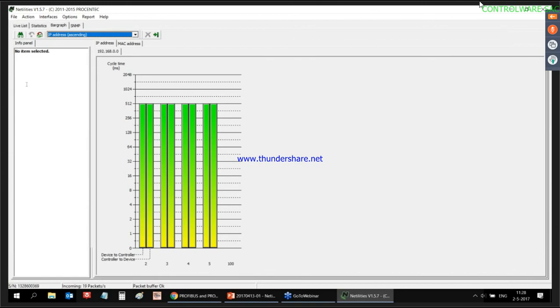By big, I mean tens or hundreds of devices on your network. Every device set at 2 milliseconds sends one message in each direction every 2 milliseconds, so your mirror port needs to handle it.